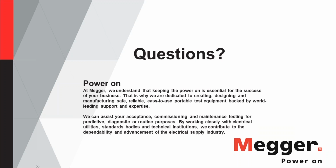So how do you measure the magnetizing current? You have the ratio as mentioned by the manufacturer. What you do is you apply primary voltage and measure the secondary voltage on any of the taps. Let's say your ratio is 1,000 to 1. You apply voltage on the primary, and you measure the voltage on the secondary.